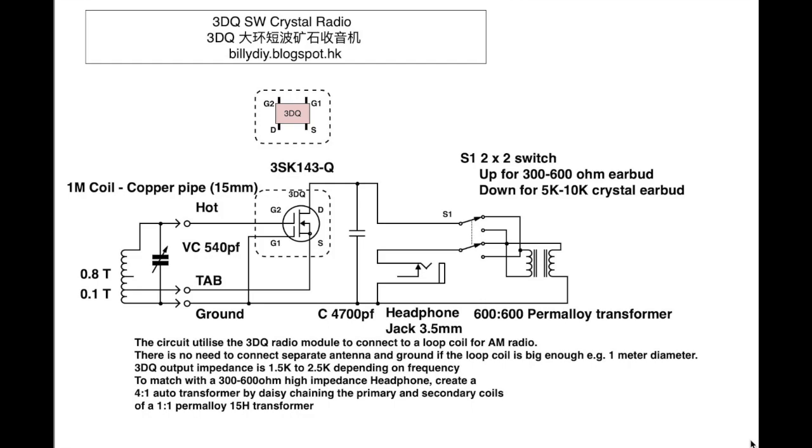So we need around 3 meters of these pipes to create a coil, which will be measured diameter 1 meter. And then this coil, we need just 1 turn or less than 1 turn, so around 0.9 turns actually. We need to keep an opening of around 10 to 20 cm on one end, so we can connect the ground and the hot of the coil to the circuit.